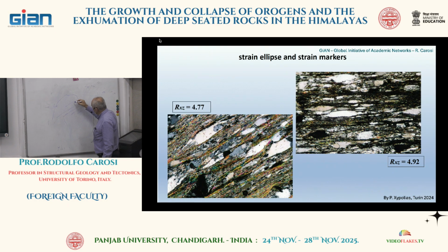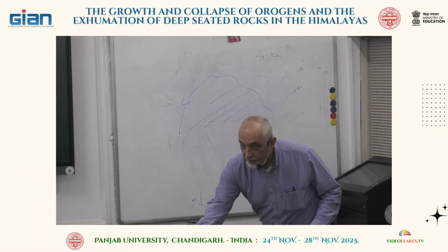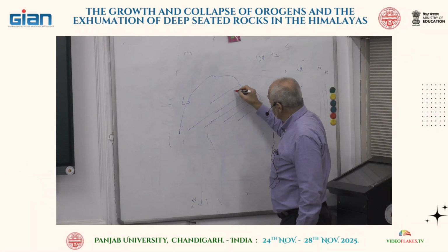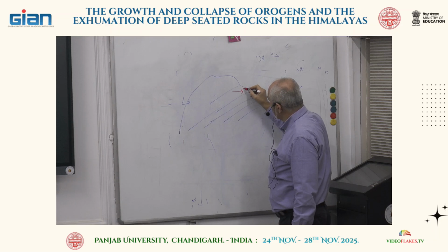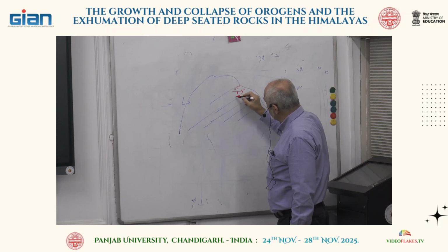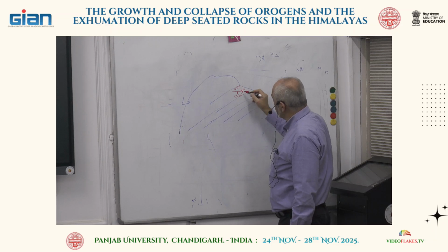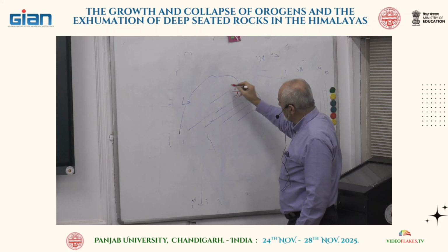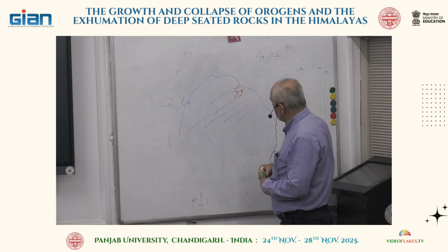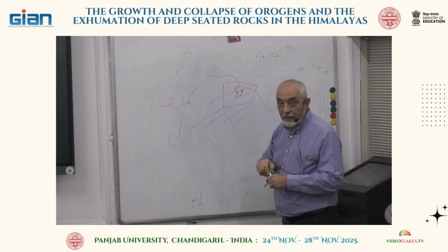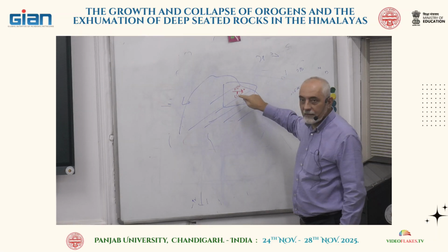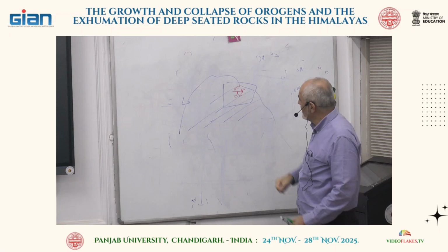You mark the orientation, the strike of this surface, marking the direction of north, the dip, maybe north 120, 55 degrees toward the southwest. This is the orientation, and you mark it on the sample. Then you break the sample with the hammer. Usually it breaks just when you put the orientation.